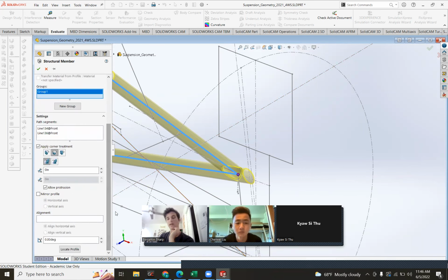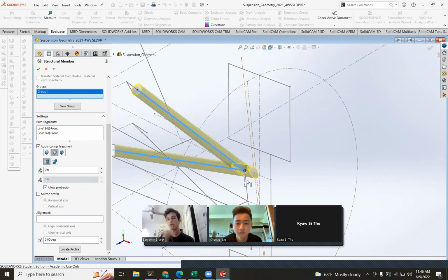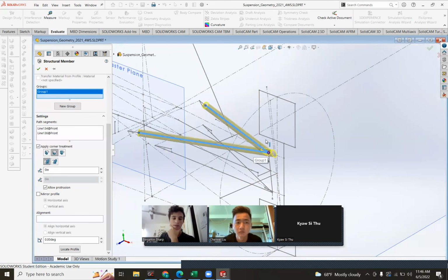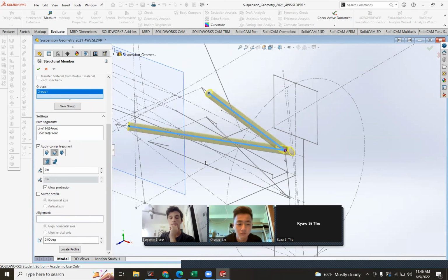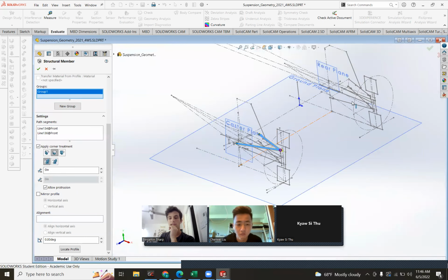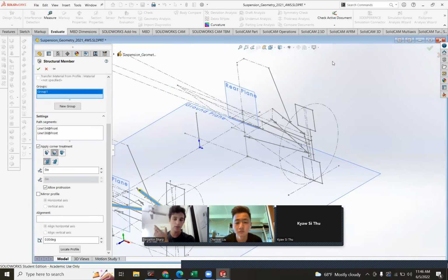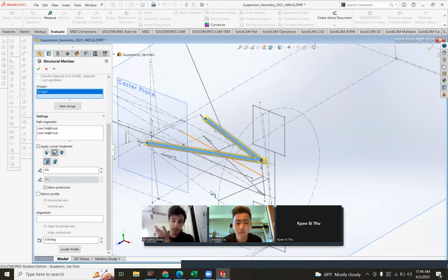You are gonna have to do a lot of cuts and modifications to these tubes after they're made for the wafers to be included. But for the simpler tubes like the tie rod, and if you have no 4-wheel steering, the tubes back here which don't have spherical bearings and wafers, you can just basically leave them as is and you're done after you do the weldment.